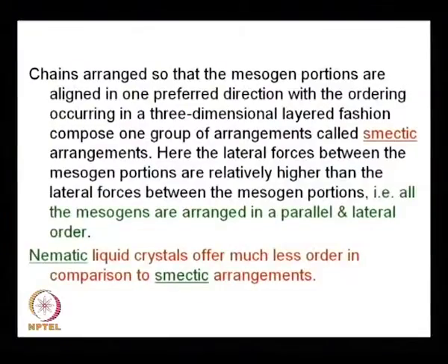Since intermolecular forces of interaction through these small mesogens are less in case of nematic, nematic LCP exhibit lower viscosity than that of smectic LCP. Clear? Now, you understand why these nematics have characteristics of lower viscosity than that of smectic one.